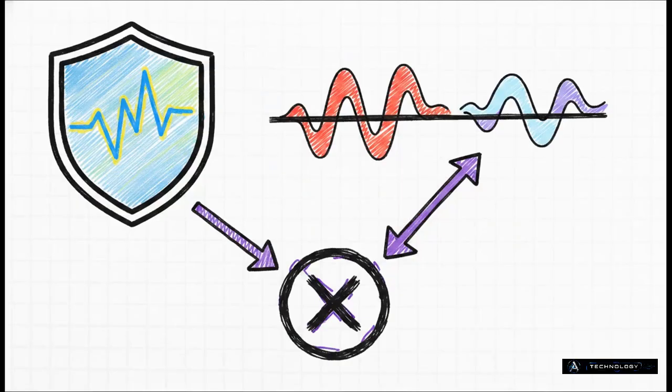Let's do a really quick recap of what we've covered in today's explainer. First, BIBO stability means a bounded input strictly gives a bounded output. That's your global safety check. Second, we find a system's frequency response by evaluating our transfer function on the imaginary axis, which shows us how it changes amplitude and phase. And finally, the locations of the system's poles secretly control both of these outcomes. But hey, this is just the beginning of our journey. In our next explainer, we're going to dive much deeper into analyzing these frequency responses using Bode plots.